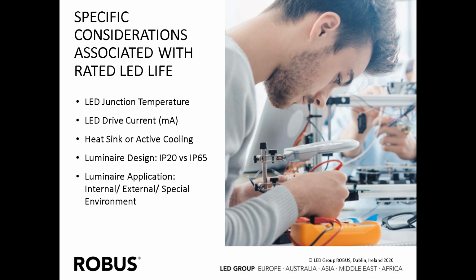It's really important that the temperature at that point doesn't increase past what the manufacturer recommends for it. Similarly, the LED should be driven at the right current, so it's not overstressed, driven too hard, and starts to get hot, so the junction temperature increases and it causes a problem for the life of the product.